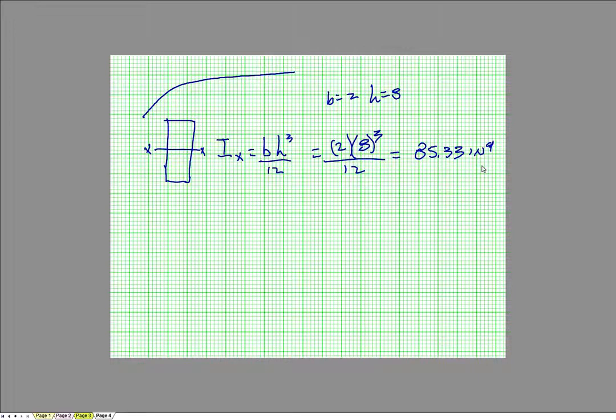Even easier, if it's structural steel, in all of those pages in the appendix, I believe 1 or something like that, all the moments of inertia are provided, depending upon its orientation, of course. Just like the rectangle, an I-beam that's that way is going to be much stronger than an I-beam that's that way because it's taller. Okay, and those moments of inertia are actually provided in the back of the book.